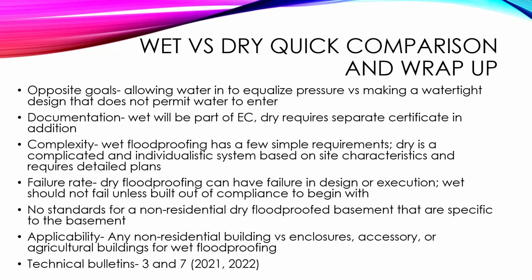So dry floodproof non-residential buildings can have basements if they are meeting those design requirements. The applicability, non-residential buildings for dry floodproofing, or we're talking about enclosures, accessory, or agricultural structures for the wet floodproofing. And then, of course, those technical bulletins that I showed you and FEMA publication 2040.